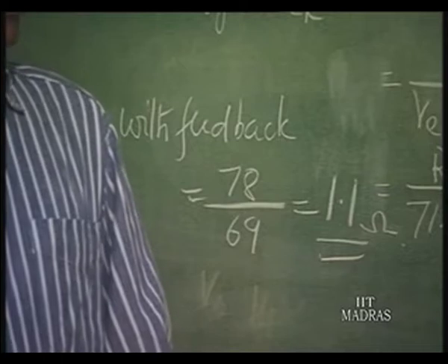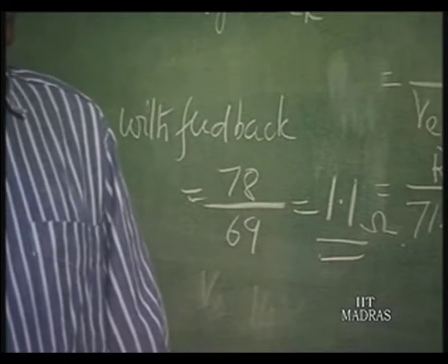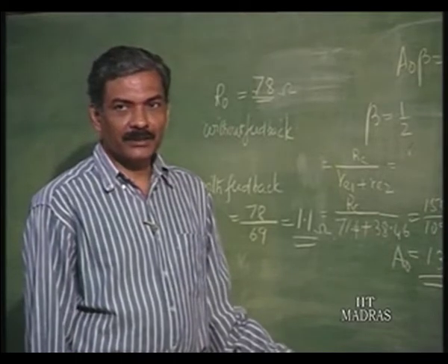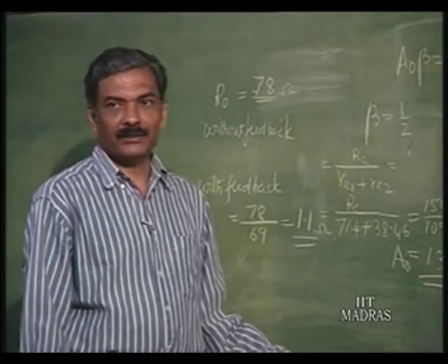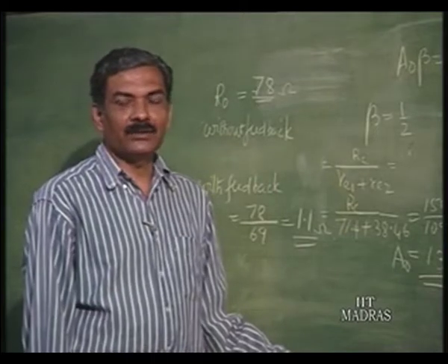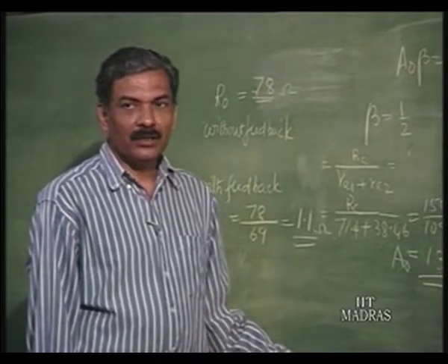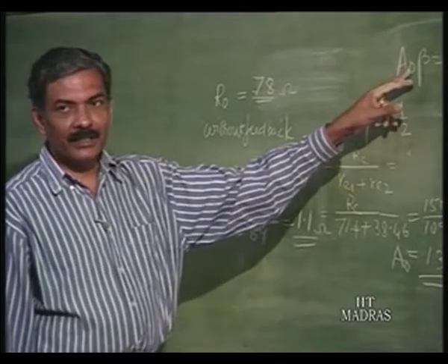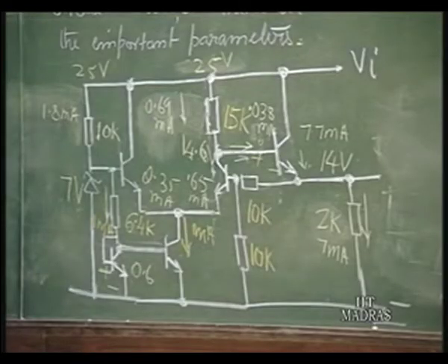One thing that you have to remember is this is a feedback structure, and that is why it is giving pretty low output impedance. If you use an op amp, it can become fractions of ohms, but that is valid only for low frequencies. At high frequencies, you cannot assume this kind of gain, the loop gain reduces and output impedance increases.